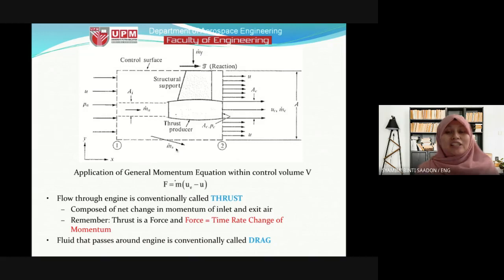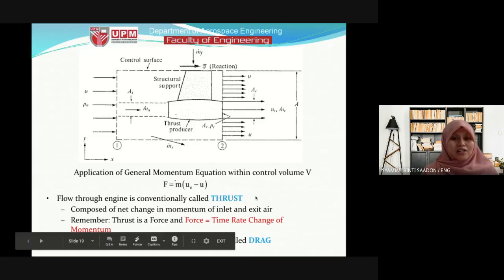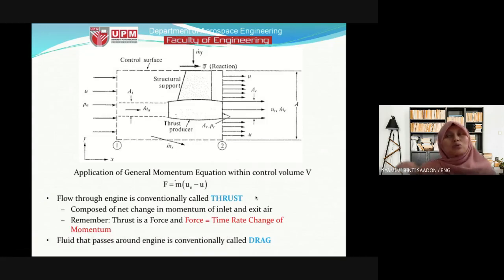We define the thrust equation from the momentum equation, which is Newton's second law. From this theory we achieve the thrust equation, which we are going to use many times throughout this semester, throughout this propulsion course and in your future, inshallah. So try to do this. Try to consider this control surface as a closed system.